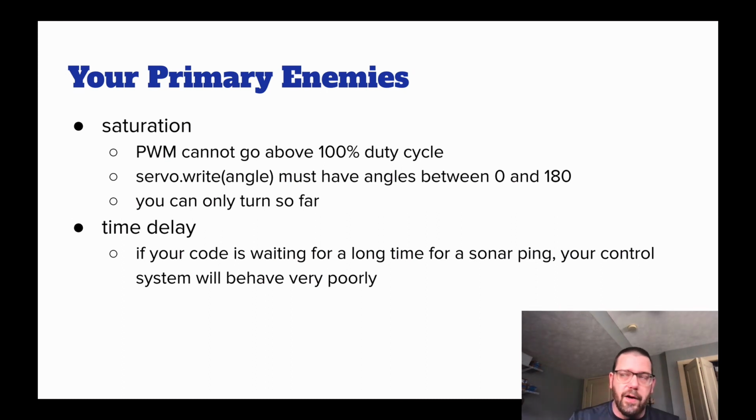So be aware that saturation is going to mess with you, and try very hard not to make your code have too many pauses in between the times that you're doing these control actions, because that's going to get really weird. For example, I don't think we have this problem as much with RoboRace as we might with RoboSaki, but Sonar takes a few milliseconds because you're reading that and sound has to travel a certain distance. So just be aware of anything in your code that would cause it to have pauses between its control actions, because that can be really, really weird.